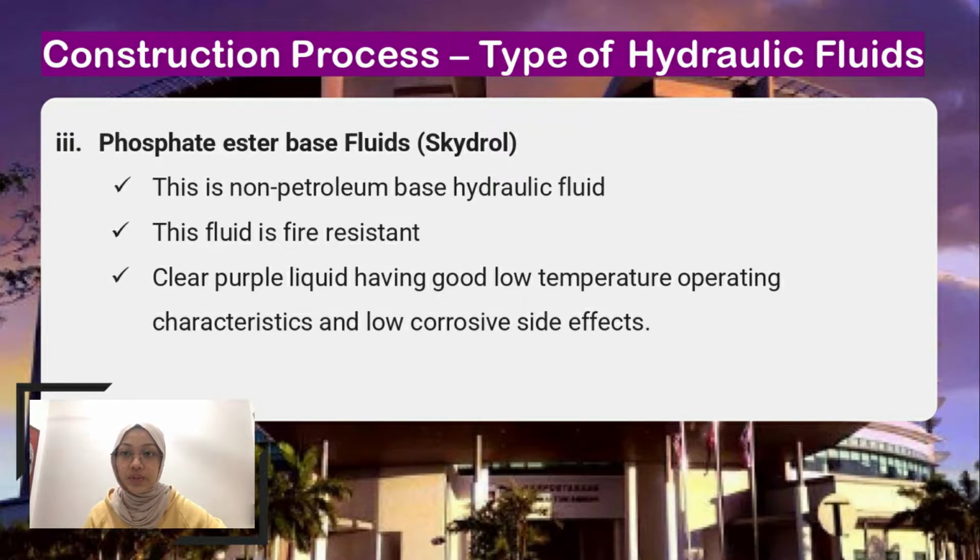Number 3 is Skydrol. This is a non-petroleum-based hydraulic fluid. This fluid is fire-resistant, a clear purple liquid having good low-temperature operating properties and low corrosive side effects.